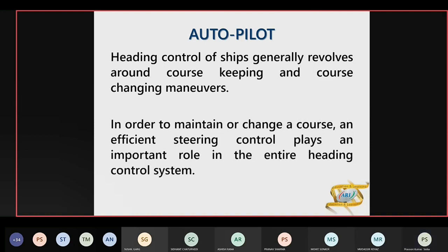You don't have to. If it is PID system, you have to do. If it is adaptive, then it will widen because it will see that I'm giving rudder, nothing happens. The ship is still off course, heading is changing constantly. So it understands that, okay, weather is bad and no matter what, the waves are throwing the head to this side and that side of the course. So it sees that there is no point steering right now, so let us widen it.